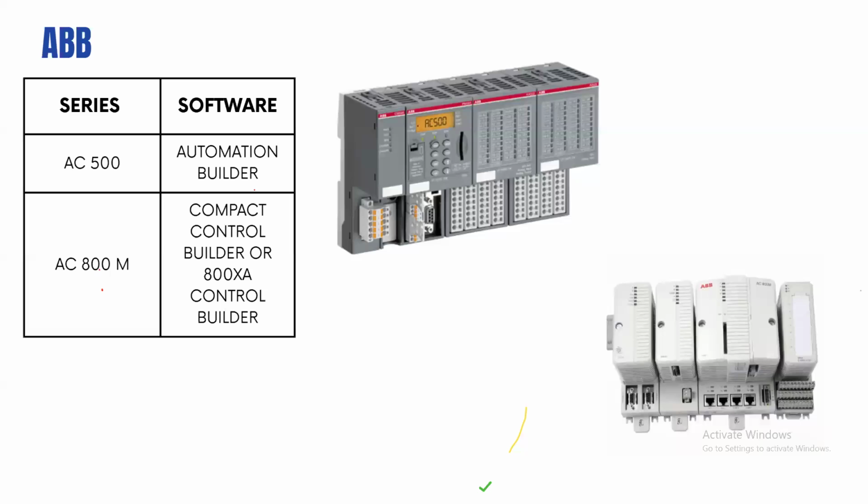Yes, you can. You can do anything you want. It doesn't have to go back to the PLC. Imagine you want to show that the motor is running. If you have a lamp, you connect 24 volts to one end of your auxiliary, then the other output of your auxiliary goes to the positive terminal of your lamp, and the negative goes to a ground somewhere. Because all we are dealing with is voltage and current, you can wire it however you want. Instead of that signal going back to the PLC, when that contactor is energized, the output of that auxiliary goes to your lamp and indicates that your motor is running.